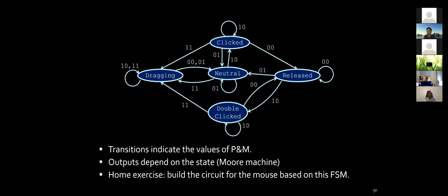You're going to first build a state table, like we practiced before. You're going to have these different states with the names first, and then you take those inputs and generate outputs. And the outputs also depend on the states. After that, you would start to convert all these English words into flip-flops. You're going to figure out, hopefully based on the math we did, how many flip-flops you need, you're going to use them, and then you're going to define a state table.